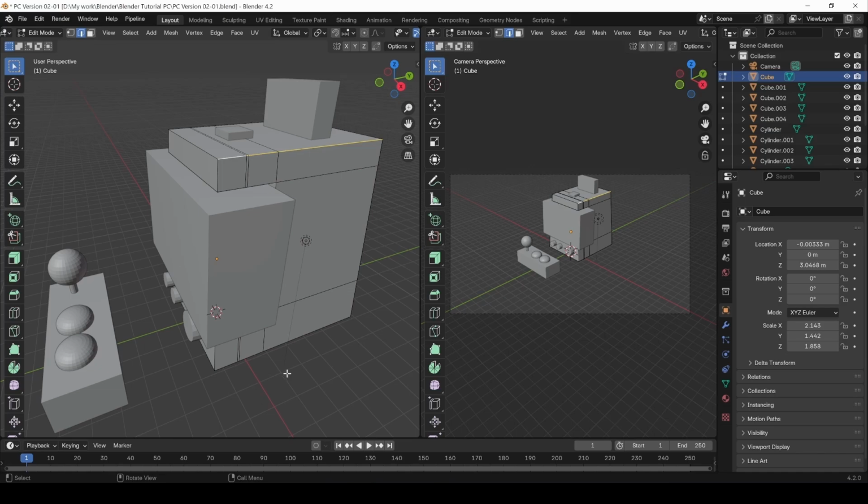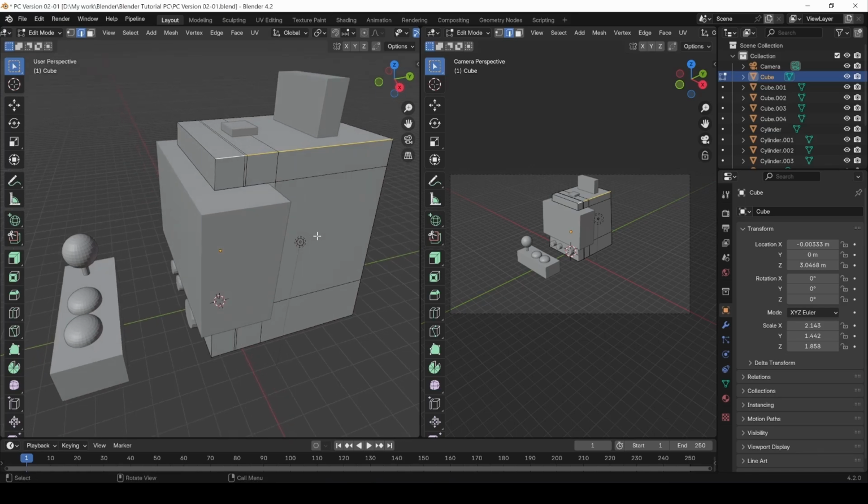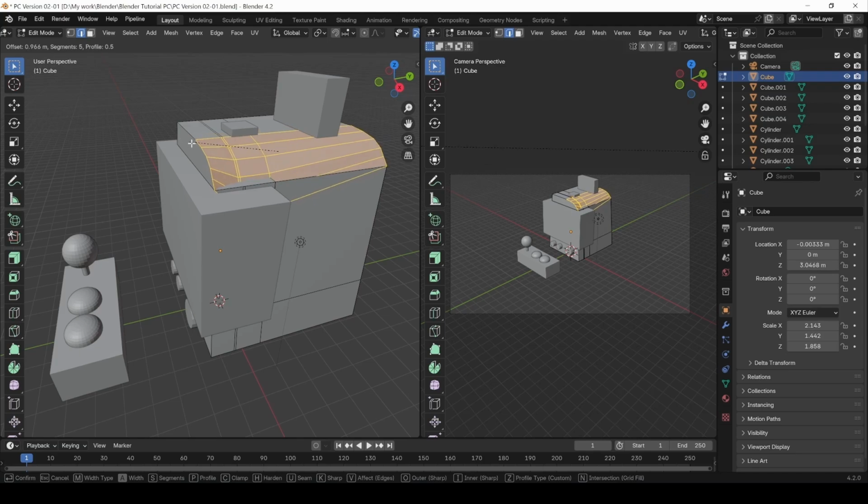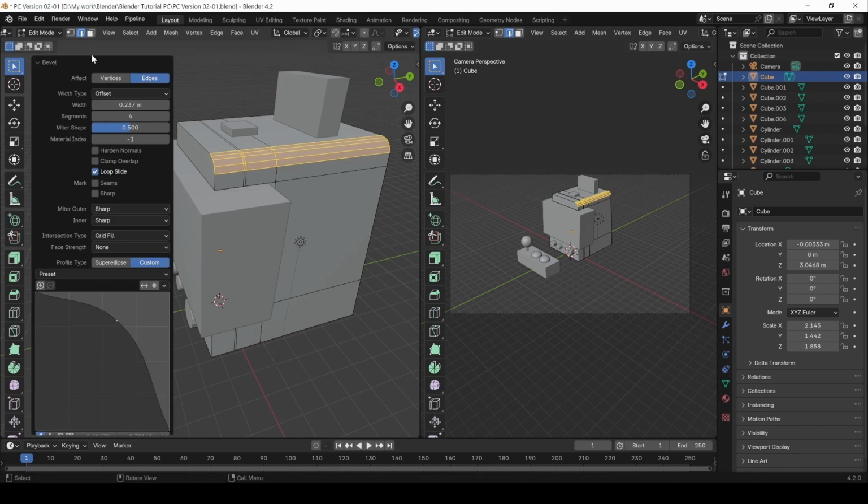Let's do selection mode again. The shortcut for this is Ctrl B. If you press Ctrl B, you will get this, which allow you to do the same thing. If you move it, you precise how big it will be. Scroll up and down to precise how much edges you will need, and when you press to confirm, you will get the same options that you had before.